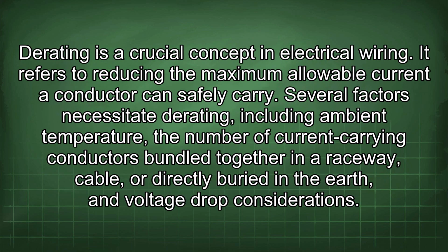Derating is a crucial concept in electrical wiring. It refers to reducing the maximum allowable current a conductor can safely carry. Several factors necessitate derating, including ambient temperature, the number of current-carrying conductors bundled together in a raceway, cable, or directly buried in the earth, and voltage drop considerations.